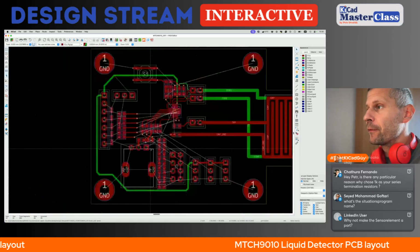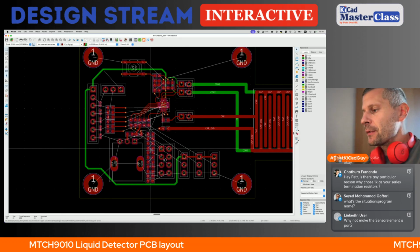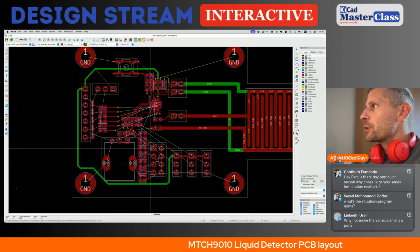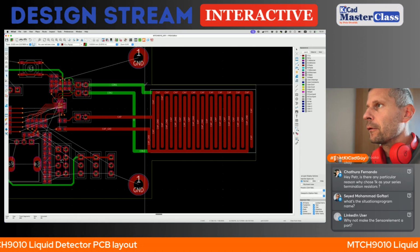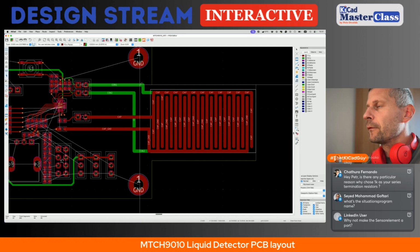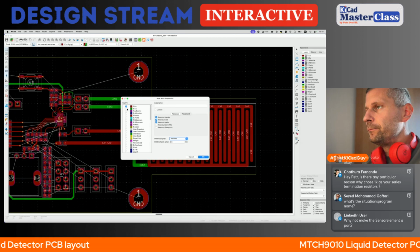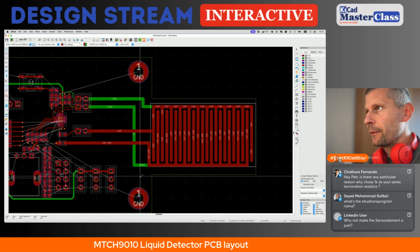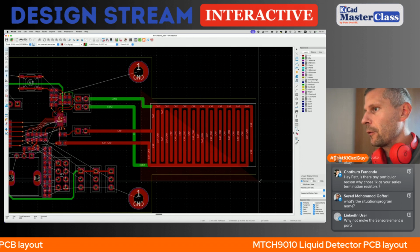It means that I have to focus only on 3.3 and keep in mind the return path of the ground that will be on the bottom layer, with an exception of this section. There will be no copper pour. No copper pour here, or let's say here. No copper pour. Yes. Here, no copper pour.